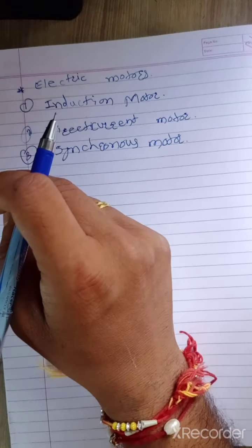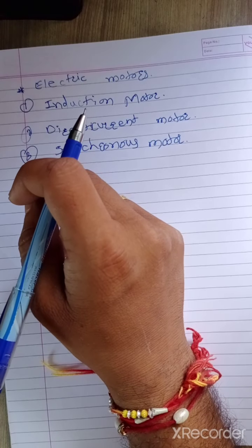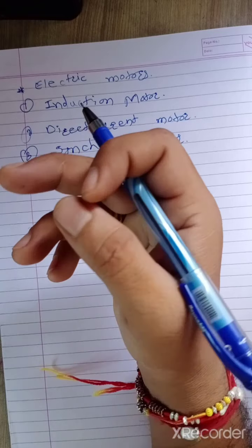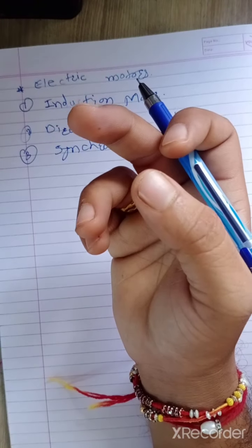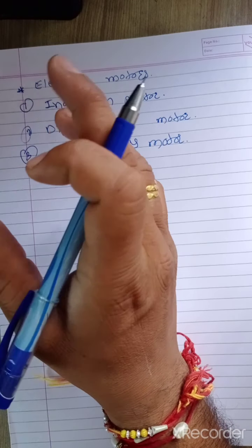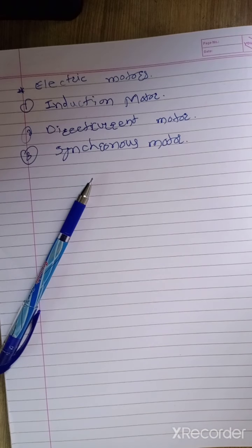While induction motors rotate with slip, that is RPM less than the synchronous speed, the synchronous motor rotates with no slip, that is the RPM is the same as the synchronous speed governed by the supply frequency and number of poles. The slip energy is provided by DC, and this may be called excitation power.